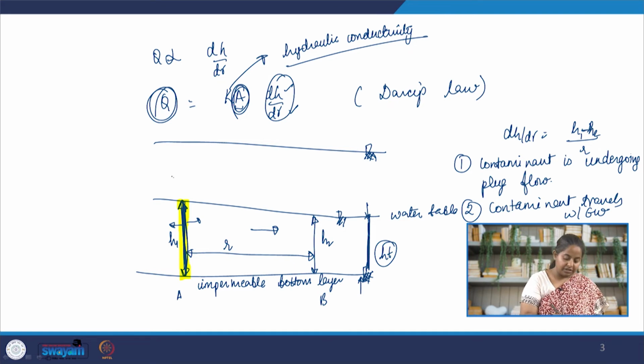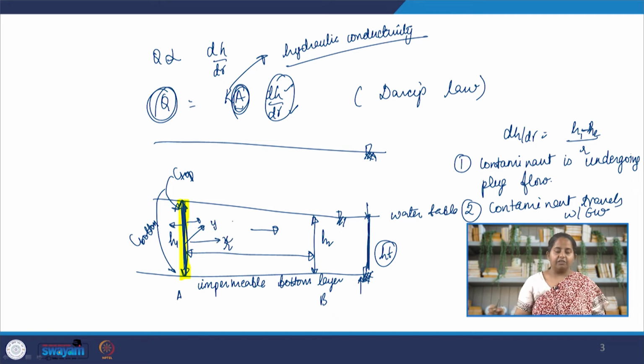So the concentration at the top is the same as the concentration at the bottom of the aquifer for a given plug. So now we can make this a two-dimensional model and only work in the x and y axes, and forgo the z axis. This is how we reduce a three-dimensional model into 2D.